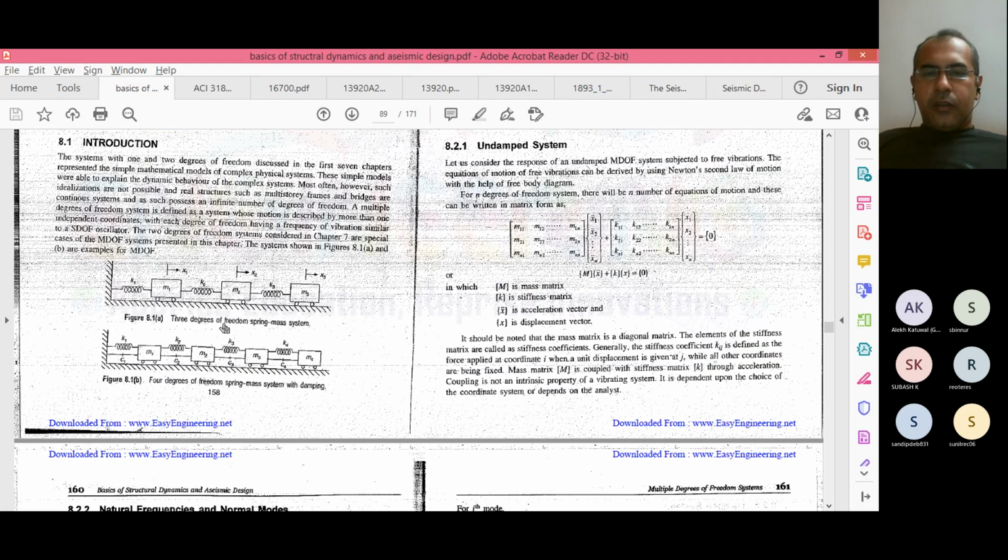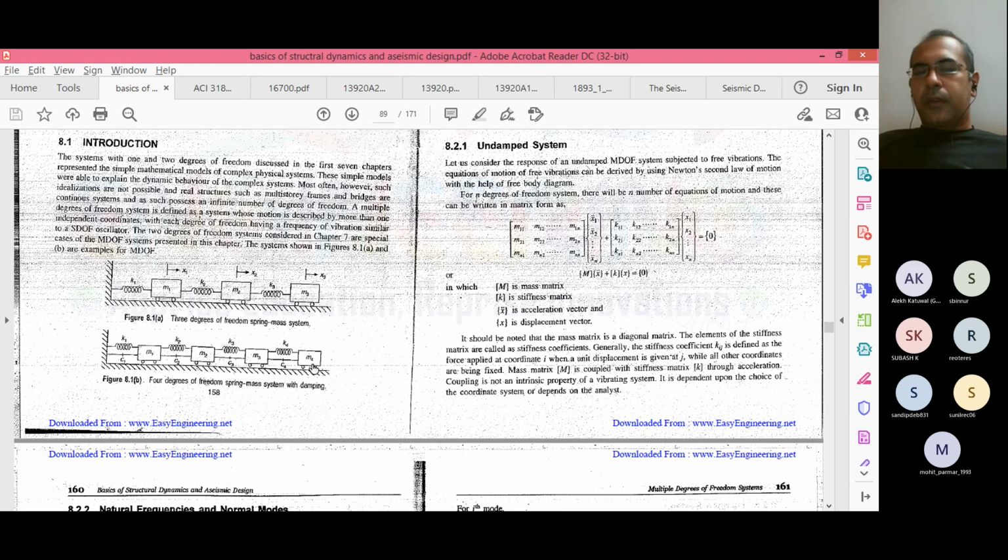Okay, so you can see mass m1, mass m2, mass m3, or 1, 2, 3 and 4. Four masses are there, so this means a 4-story building. Our building is a 7-story, so there will be 7 masses: m1, m2, m3, m4, m5, m6, m7. However many stories there are, that many masses you need to assign here. This is the mathematical representation of your building.